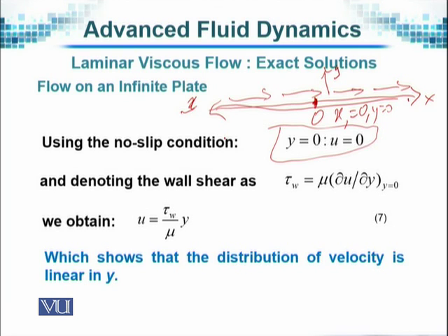And then, of course, by taking the integrations of different values that we realized, we will have the wall shear, that is shear at the wall, to be denoted by tau. Remember that by tau we denote the shear forces, and w here only denotes that we are calculating it at the wall.